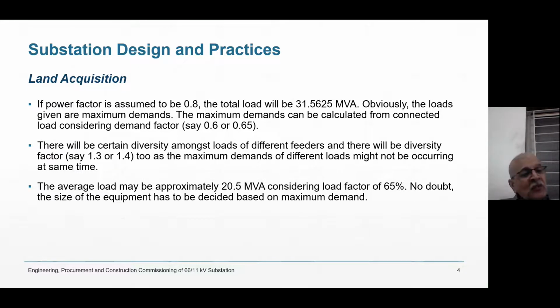So the lights will be on, fans will run, but the three-phase motor cannot run. So the main load, that is industrial load, that caters for industries, will not be available for that district. That is a forced diversity. Government is by force not giving load to them. So thereby you can reduce the load. That means the maximum demand, which we have calculated here, but the actual maximum demand will be less by this divided by 1.3 or 1.2 or 1.4, whatever is the diversity factor.